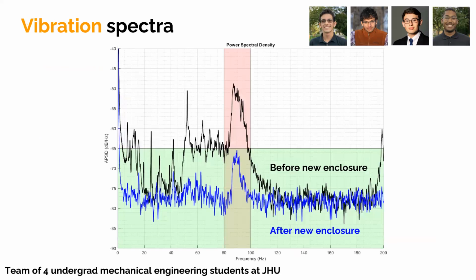We also tracked down some of our vibration sources at the same time. They went through the entire setup, tracing an incoming vibration from our wall throughout the system, acoustically and mechanically vibrating the mirrors inside, and we tracked it down. And we eliminated that chain of vibration transmission there. So we are now not limited by vibration anymore. We're now limited by chromaticity and actual things that we are interested in studying.